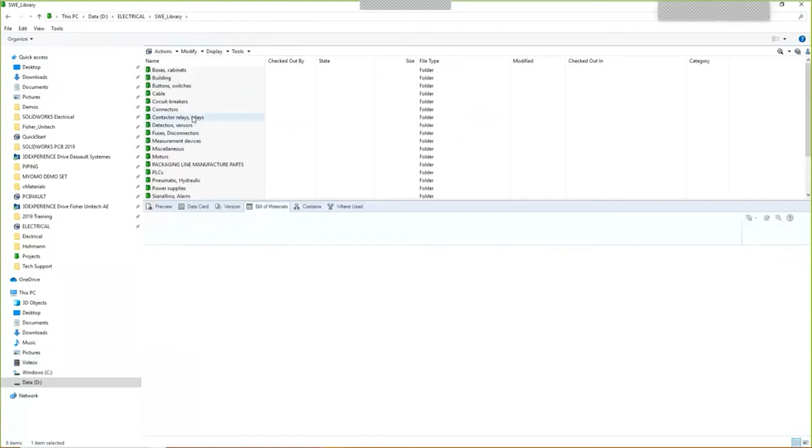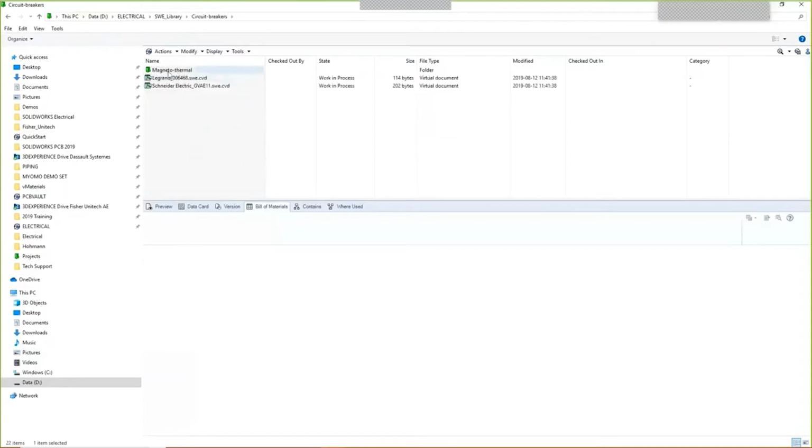That way, if you go to the electrical portal and you're downloading Rockwell Automation libraries and you're getting like 1,000 components, but you're only using like 50 or 60 out of those 1,000, you're not syncing all of that other information that you may or may not be using. You're only putting in the vault what you're actually using. So if I go to, you know, circuit breakers, because I was on there, if your components are not tied to a class, or a subclass I should say.